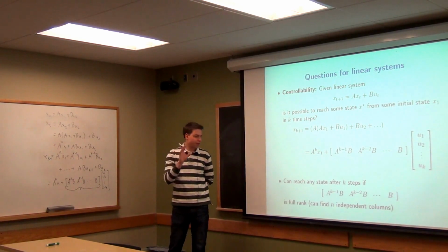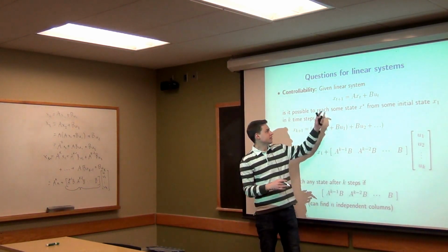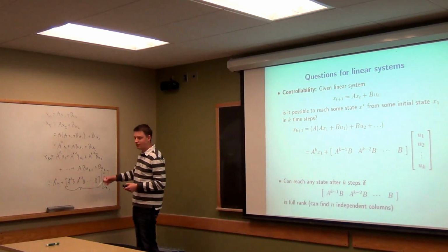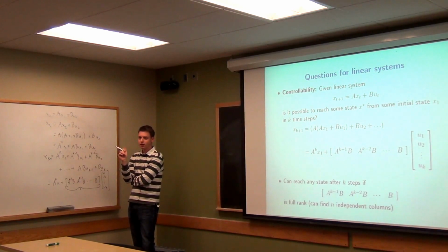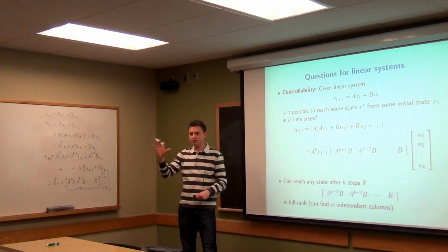Essentially, it means, I guess n is the state dimension, you have to be able to pick n different columns here, such that you can invert that matrix. Then you set all the other u's to be equal to 0, and you pick those 4 ones to be the inverse of this thing.